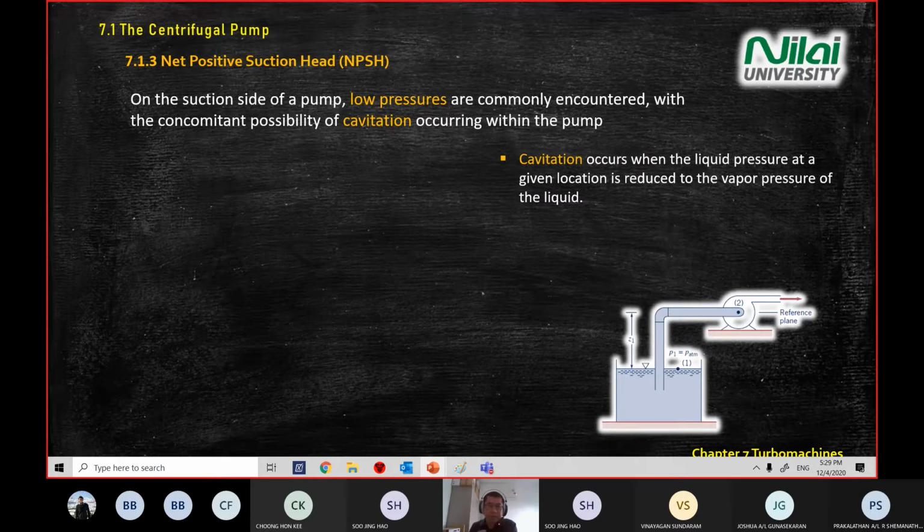You'll create bubbles. You'll see water bubbles accumulate in the pump or in the pipe, which will make the efficiency drop sometimes. So cavitation is a scenario that we try to avoid at all costs in the industry, which means water bubbles in the pipe or in the pump.